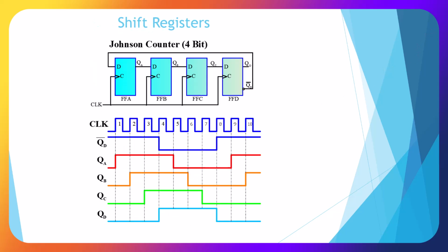Here's another shift register combination, which we call a Johnson counter. And what we're able to do is clock in a signal and then rotate it, but we put it back in. We feed it from the Q0, feed it back in, so that signal reverses continuously. So we have 4 up, in this case 4 down.